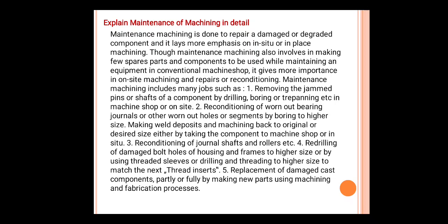Maintenance machining includes many jobs such as removing jammed pins and shafts of a component by drilling, boring, trepanning, etc. In machine shop or on-site reconditioning, worn out bearings, journals or other worn out holes or segments are bored to a higher size, weld deposits are made and machined back to the original or desired size, either by taking the component to the machine shop or on site.